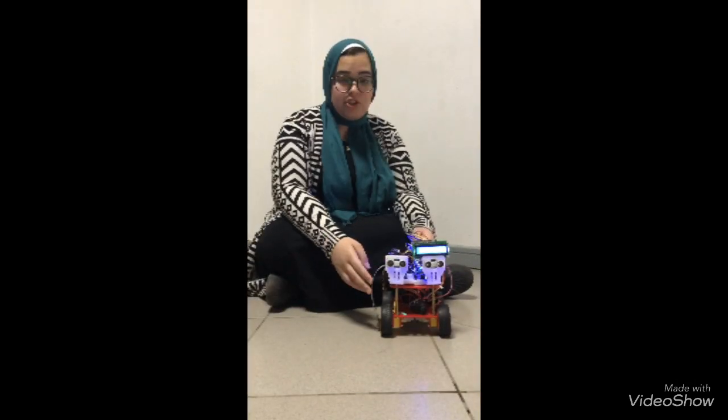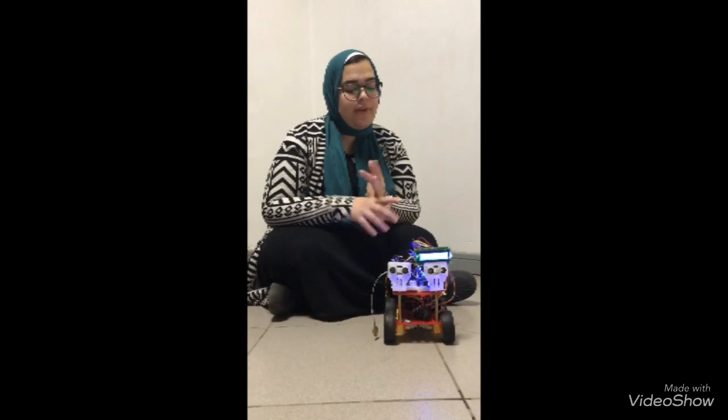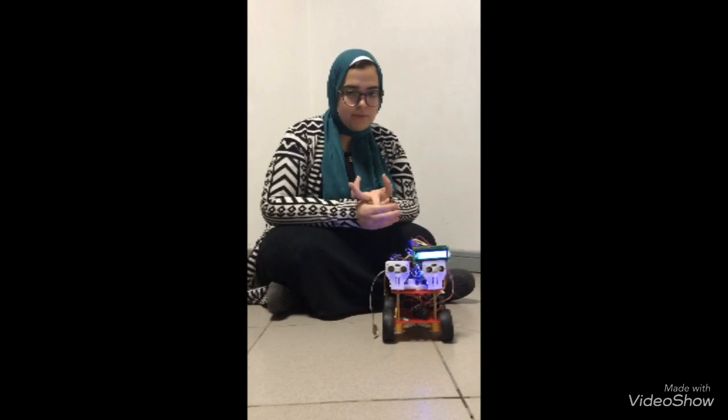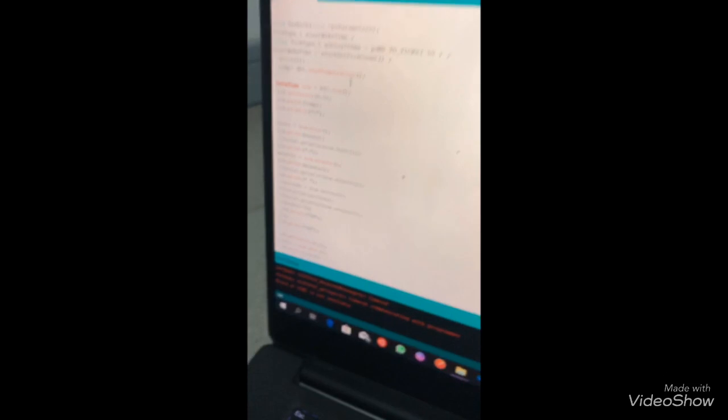In this feature, the second feature, we are displaying everything on the LCD. We're displaying the temperature, the date and time, the gear state, and also the night detection, whether it's bright or dark. So here we have the temperature sensor, the DHT temperature sensor. We read the temperature from the DHT and put it in a float called temp. Then we write the temperature we read and put a C beside it, which is degrees Celsius.